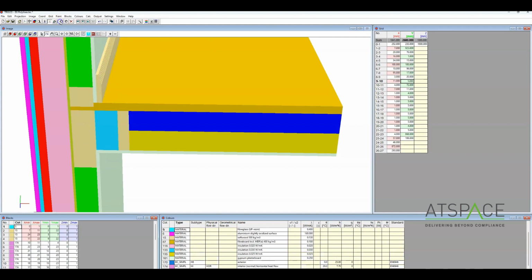So yeah, we're going to insert a new block above the top block there. This new one I've inserted is essentially going to be the lowest priority one in the whole model because it's right at the top. Just refer to those colours again because we want an internal boundary condition with a downwards heat flow, which should be colour number 175. So I'm just typing that in the bottom there.